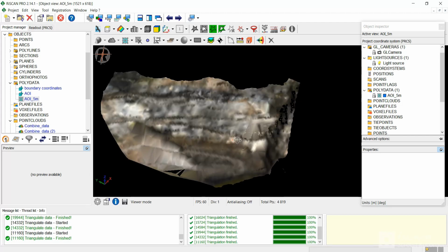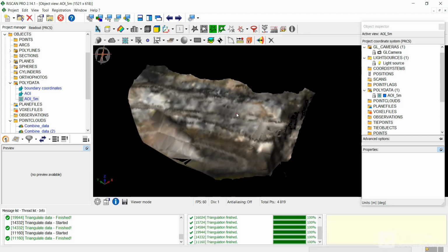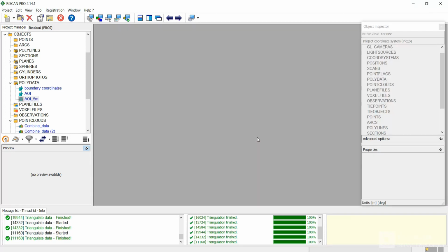Also this is the point cloud after the excavation process, so you have to make a DTM of the initial data as well, from when we had begun the excavation process. So there is again a prerequisite that you have to have the initial surface of this area of interest, and you have to make the DTM of that surface too. So close this window and I will import my initial surface as well. How to import and where to import?